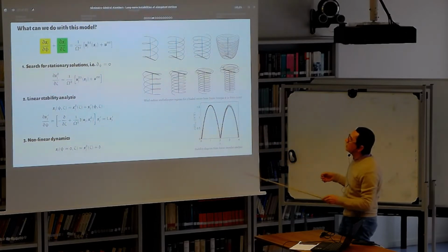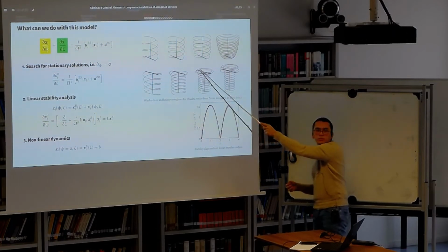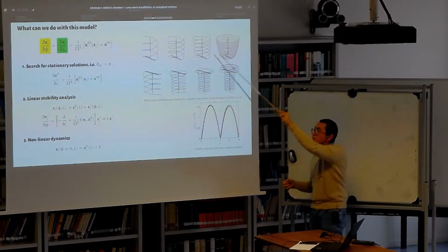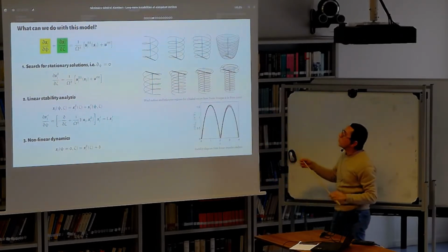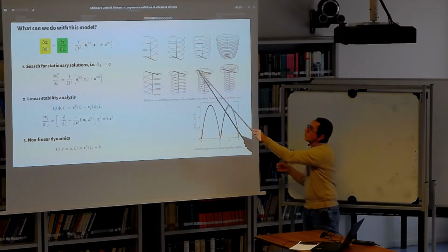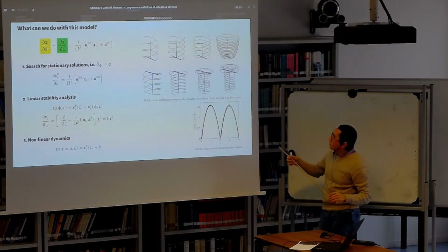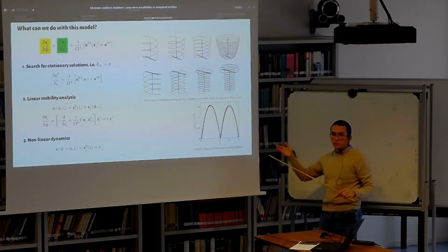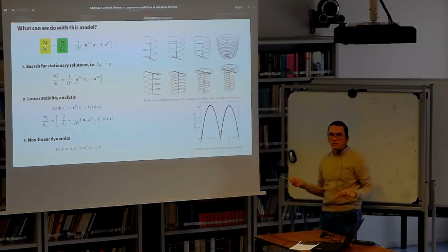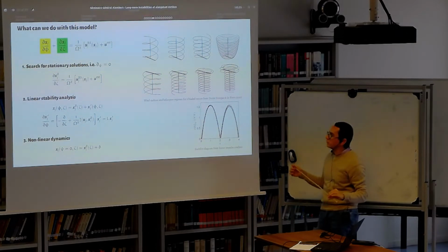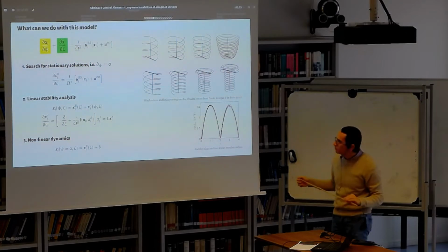So what they did is they took one of these configurations, they introduced a small perturbation near the rotor plane as a direct impulse, and they looked at how that perturbation propagated downstream. They were able to show that in most cases, since the perturbation is quickly propagated downstream towards the uniform helices, the stability properties that you are going to get at the end correspond more or less to those of the helices. So that sort of reinforces this idea of studying this uniform configuration. Okay,